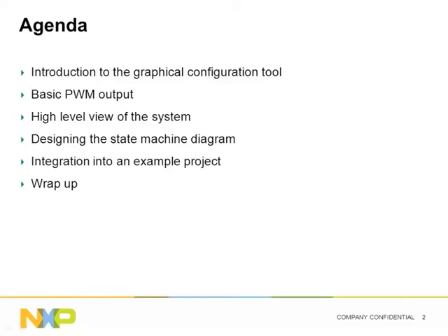In this case, it will be the control logic for a brushless DC motor. Then, we're going to design the state machine diagram using the graphical configuration tool. At the end, we will integrate the output of the tool within an example project and build our test application.